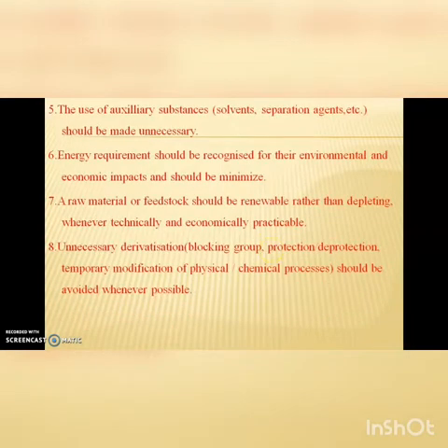Now, the sixth principle is that energy requirements should be recognized for their environmental and economic impacts and should be minimized. The use of a catalyst has the great advantage of lowering the energy requirement of a reaction. In case the final product is not pure, it has to be purified by distillation, recrystallization or ultrafiltration. All these steps require energy. So the process should be designed in such a way that there is no need for separation or purification.